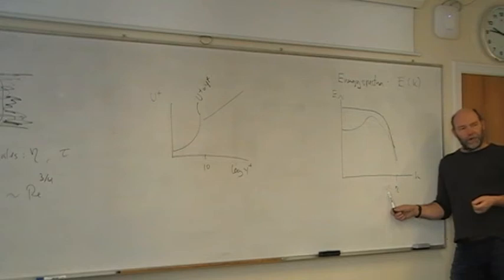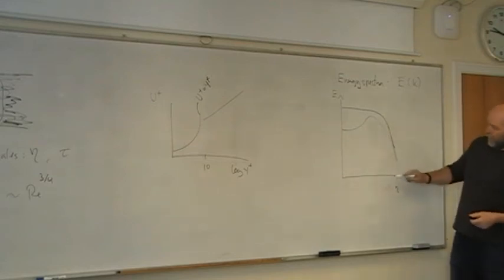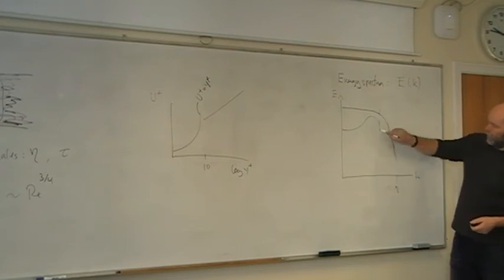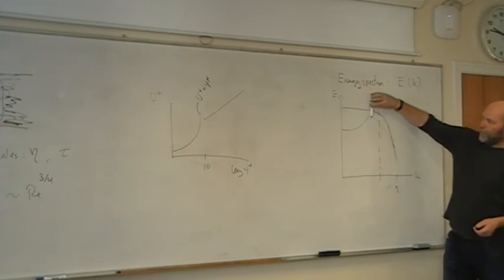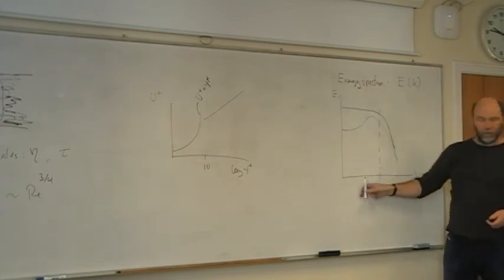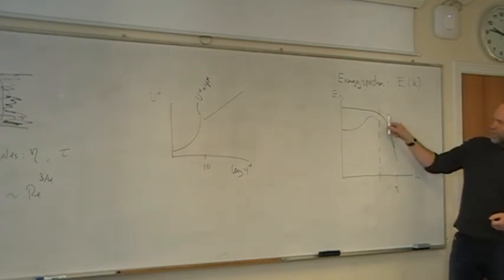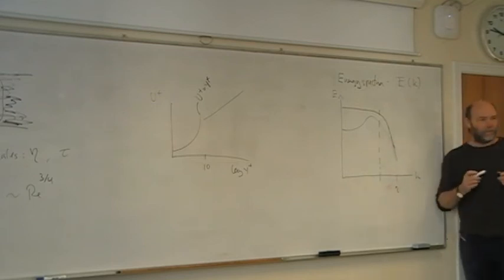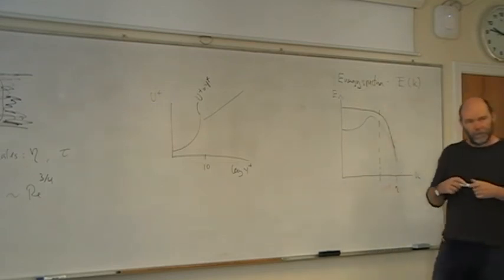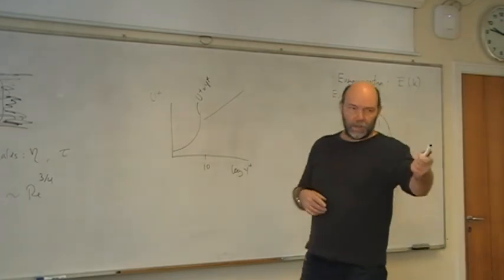Now you're talking large eddy simulation. Then you can have the cutoff maybe somewhere here and say the most energy containing behavior, there I resolve it. I have plenty of cells to describe it. But in this part of the energy spectra, I model it. So that is sort of the philosophy behind DNS and large eddy.